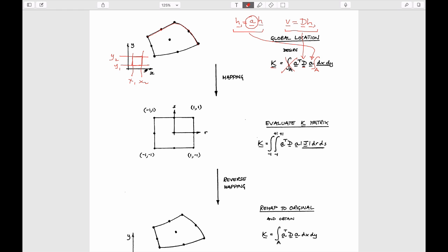So instead of that, we have this complicated geometry which we have to deal with. And the second is that if we use shape functions which map the variables, say with mid-side nodes, then by definition, as we've already alluded to, the shape functions can't just be linear shape functions where when you take the derivative of them, a term which is linear, a times x, if you differentiate a times x, it just becomes a. It becomes constant in here. So we're left with portions that actually vary within the bounds of the element.